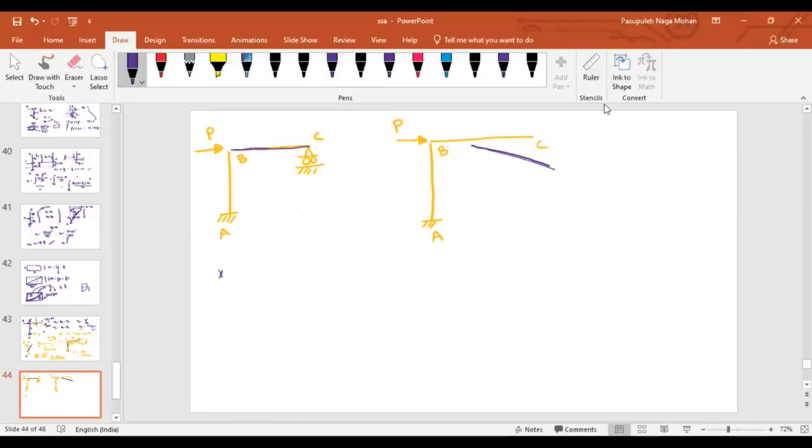Did you understand? If there is no joint at C, vertical deflection can happen at C. But yes, because of this additional support, that is also restrained. If that is restrained, how can the load path or the load distribution happen in the members? Imagine sequentially, if there is no support at C, it will behave like a cantilever, and then BC will have a simple linear deflection or rigid body rotation. Now, if I restrain this vertical deflection at point C, how are the changes going to be there?